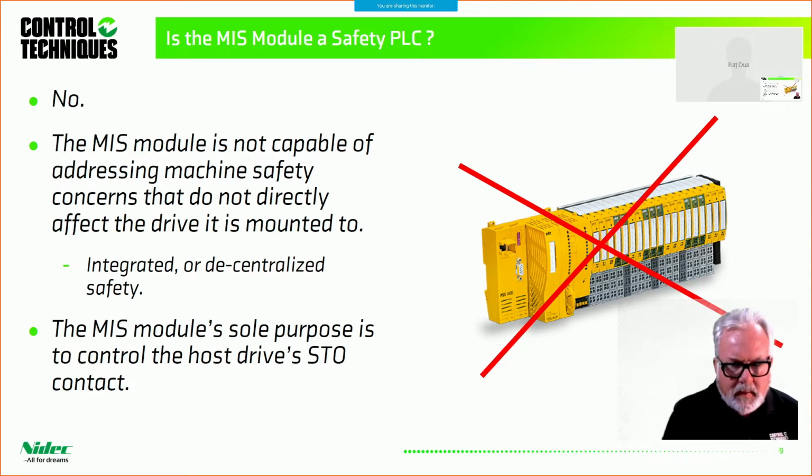So unlike the safety PLC you see there, which can take inputs from all manner of safety devices and do a comprehensive machine-wide safety application, our modules are integrated or decentralized, which means they are local to the drive it's mounted to.